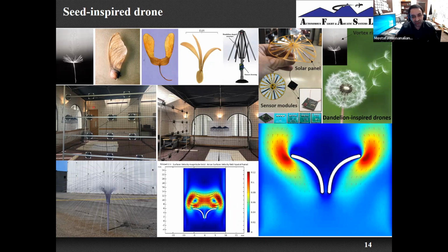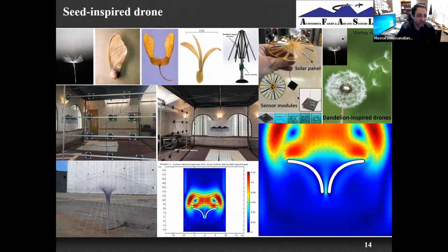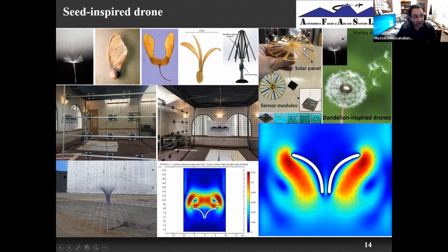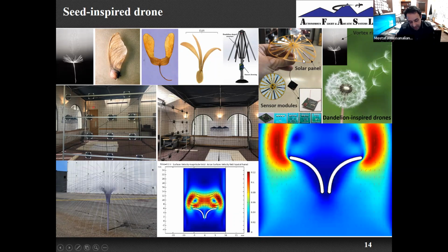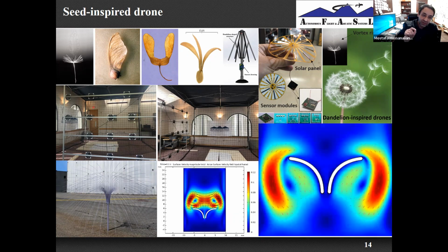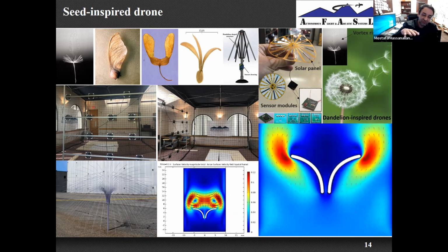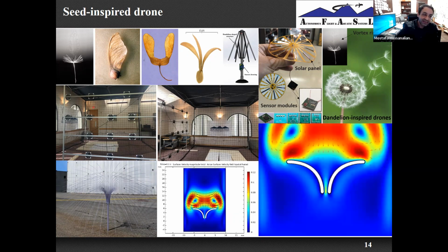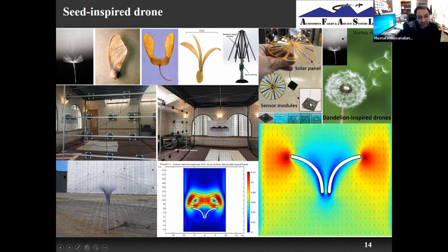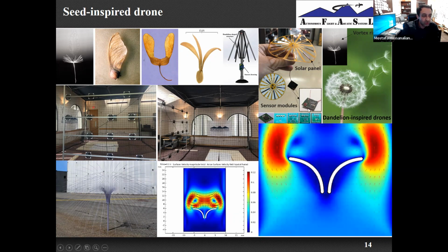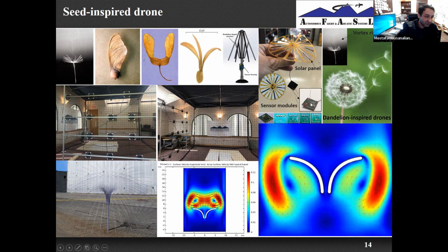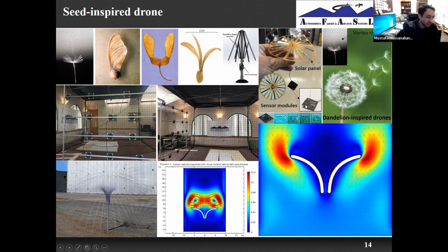And they don't need energy. They just disperse in the atmosphere. They can collect energy through solar panels or through vibration, with the new concept, the model that we are developing. We are using a piezoelectric transducer, which, with the vibration of this structure, can harness energy and provide energy to a sensor and to the communication systems, which use backscatter communication in order to provide microwatts to the system for communication.